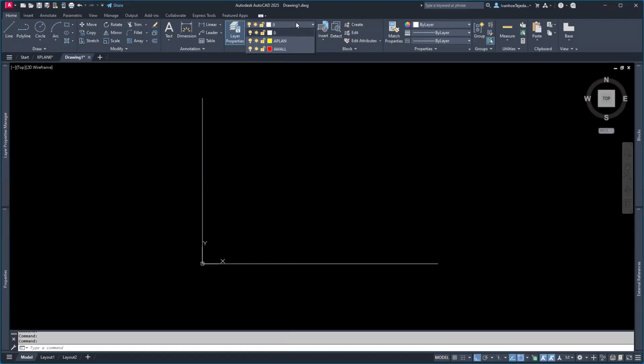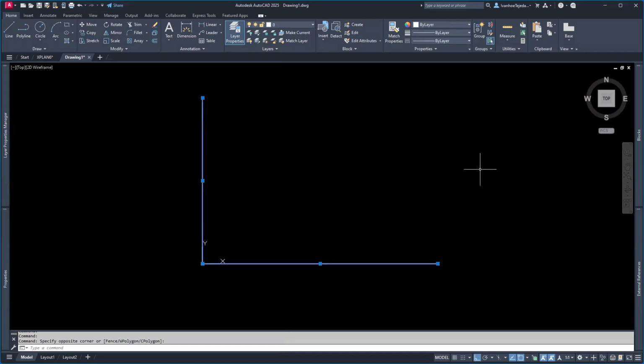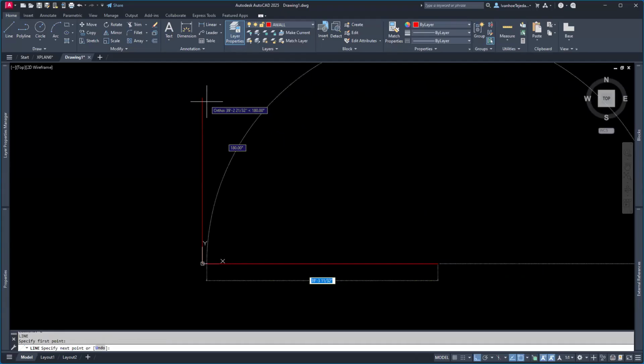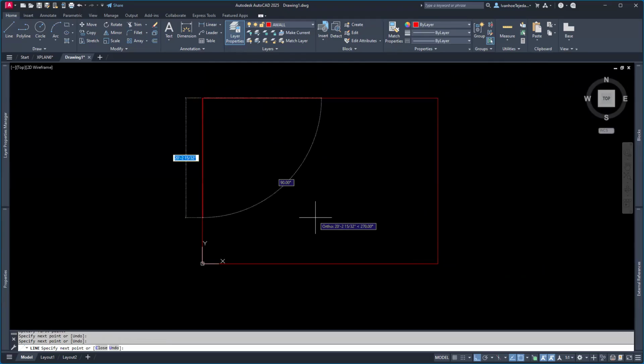Now I can go ahead and set my layer like this. And the two lines that I drew, I can just use a crossing window like this and just place them on that layer, and I'm all set. Tap the escape key, and now I'm going to draw a line over here, take it straight up. I'm tracking. I have O-Track on. I'll click here, and then I'll just click over here. Now my building is not this closed rectangle. If you make yours that way, fine, great. I'm just doing things a little different to show you some techniques here.